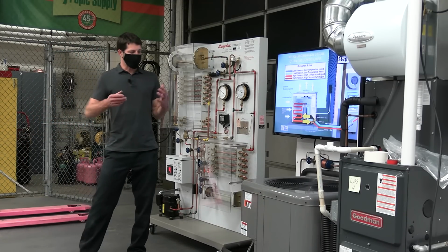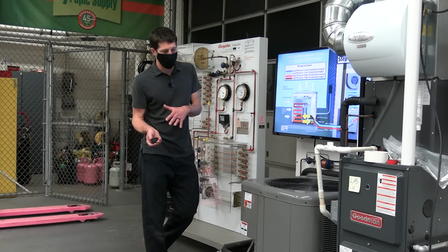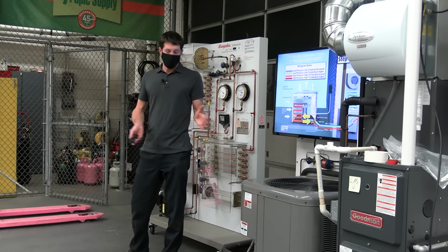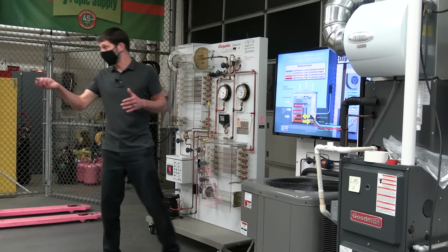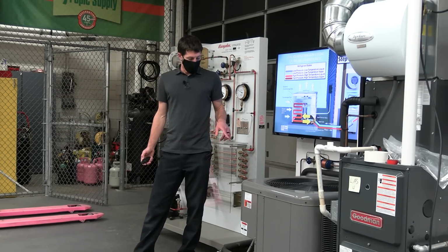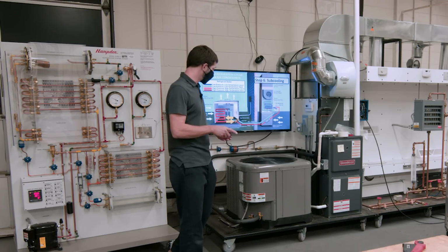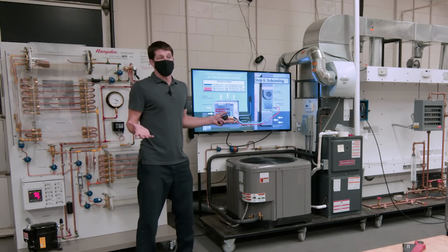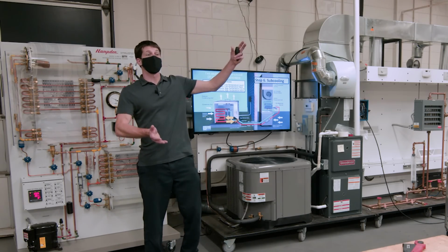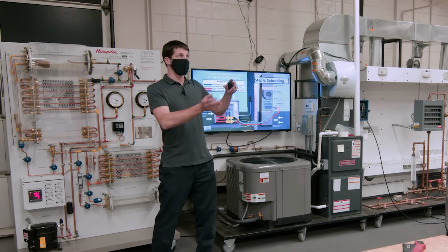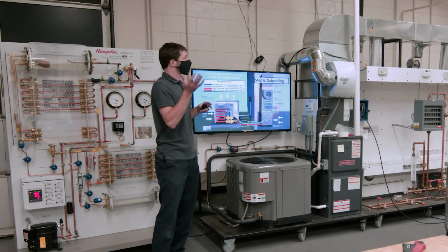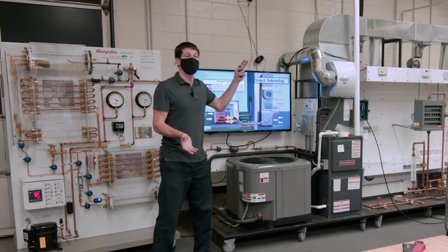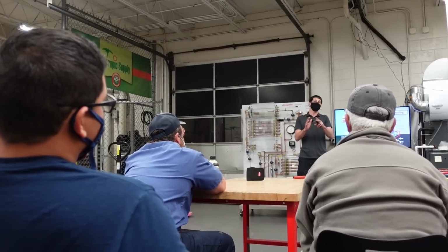Yeah, so within a normal temperature of, say, 70 degrees outside to 90 degrees outside, it's going to be pretty close to that 11 degrees of subcooling for your target. That's not going to change. Now, when a manufacturer gives you one target subcooling rating that's on here, that's basically the average from 70 degrees to, say, 110 degrees. And so if you're lower in temperature, it may be 10 or 9 degrees. And if you're up at 110, it may be 13 degrees as your target subcooling. But they just give you one to simplify it.